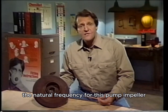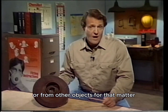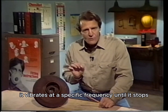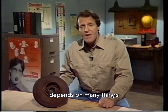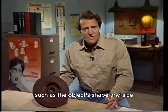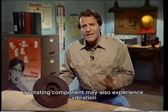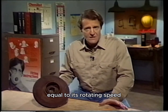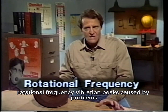The natural frequency for this pump impeller is different from other impellers, or from other objects for that matter. When the impeller is struck, it vibrates at a specific frequency until it stops. The natural frequency for an object depends on many things, such as the object's shape and size. Besides having its own natural frequency, a rotating component may also experience vibration equal to its rotating speed. The frequency of this vibration is known as rotational frequency.